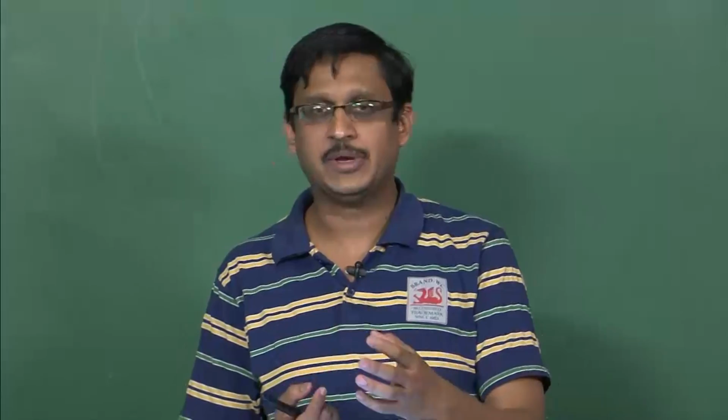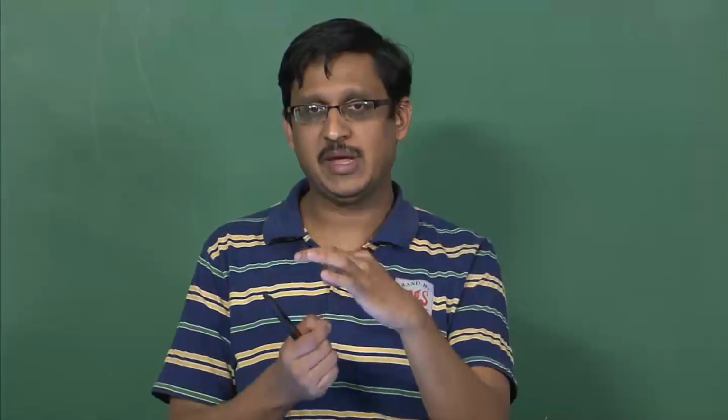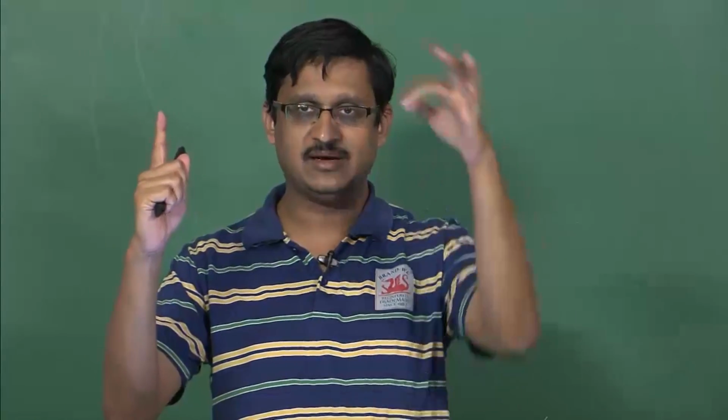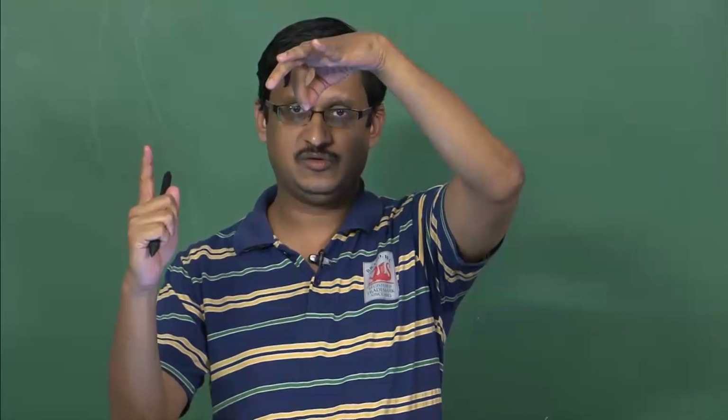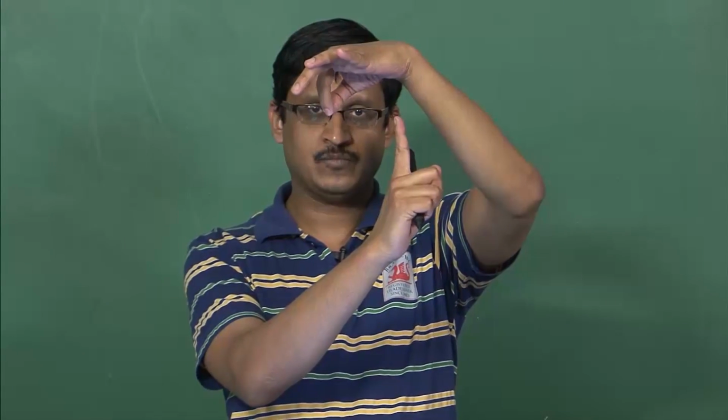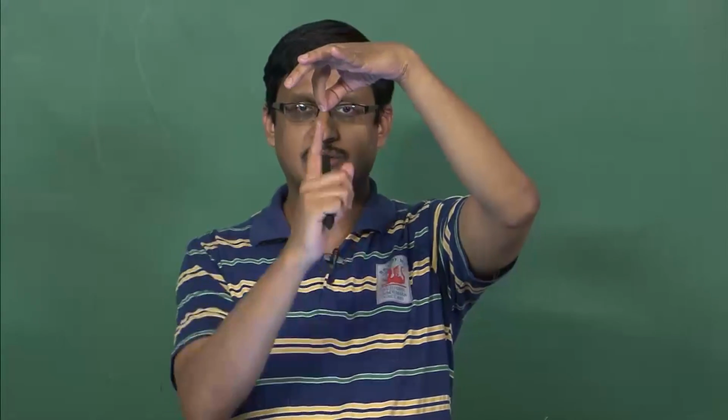Suppose I set up a hypothetical oscilloscope, well, not a hypothetical but a real oscilloscope. I set up this oscilloscope at the midway between the transmission line. So, the transmission line is of this length. I set up my oscilloscope at this point, and I launch a step voltage here. So, now I am looking at the oscilloscope. Well, until half time delay I do not see anything. There is no change that would be happening until half time delay.